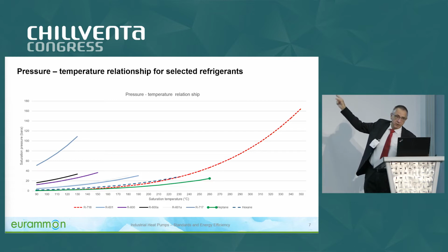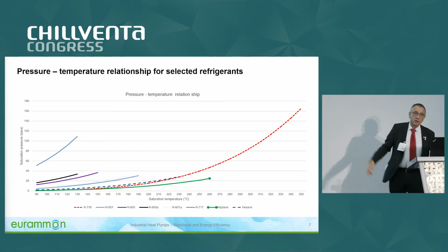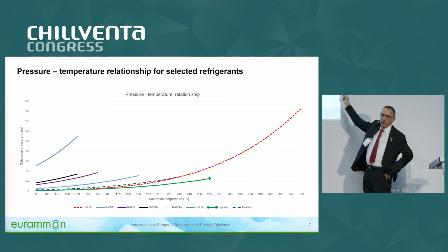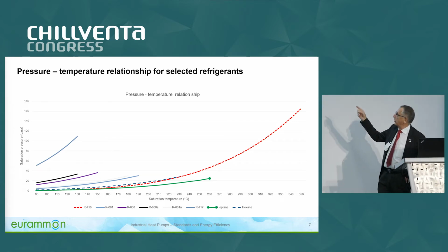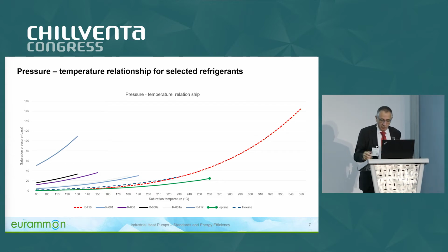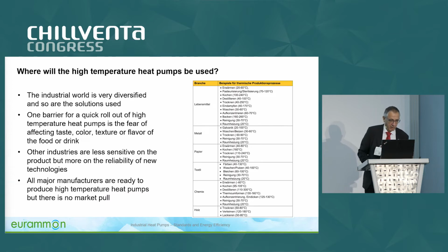You can see even water, which is the red stippled line, is at very high temperatures, and the critical point is 220 bar. When you can do higher temperatures with the hydrocarbon out here, 380 centigrade is dodecane, and you can do almost the same COP at 18 bar, so it's interesting. So there are many different parameters you have to consider when you want to select a refrigerant for the future. But I don't see CO2 or ammonia going this high. But never say never.